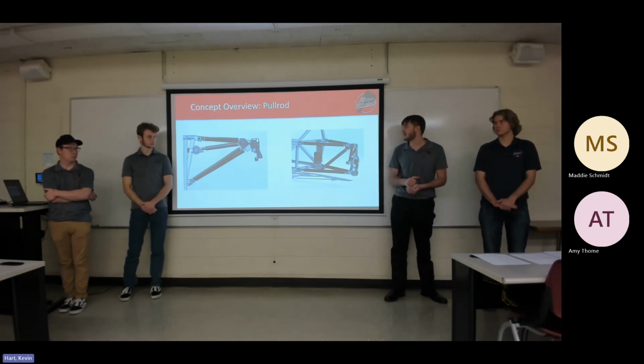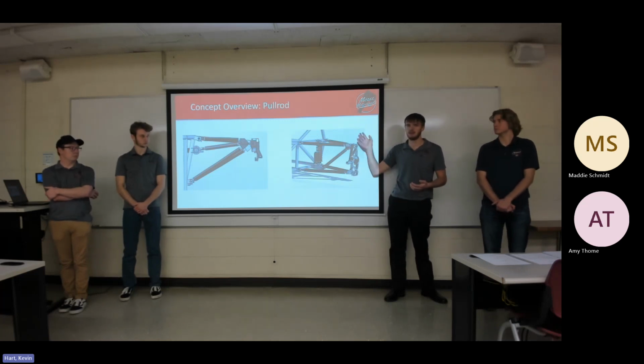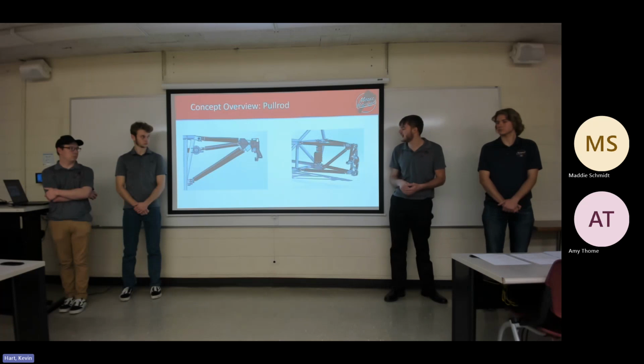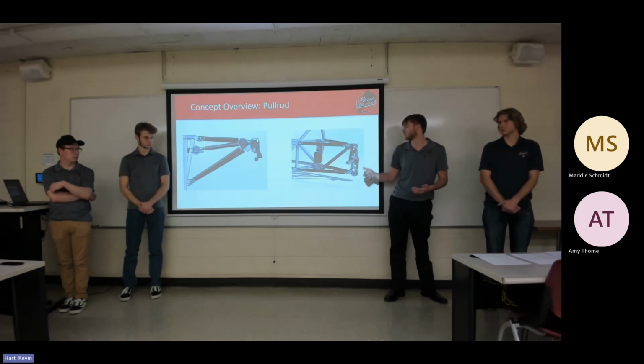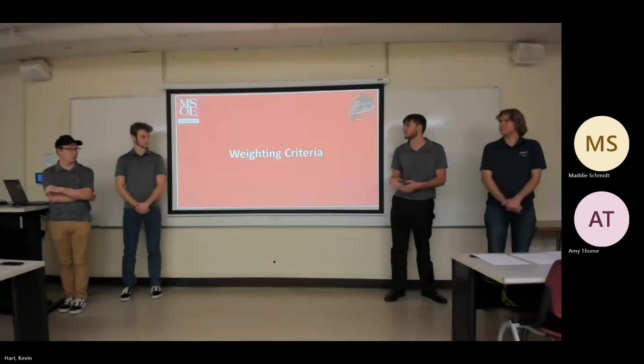However, the disadvantage of this comes in the rear of the car when the pull rod suspension cannot be mounted above both of the A-arms. So the CV axle would have to pass through both the shock and the pull rod to get to transferring power to our rear wheels, making this design likely infeasible for the rear of the car.